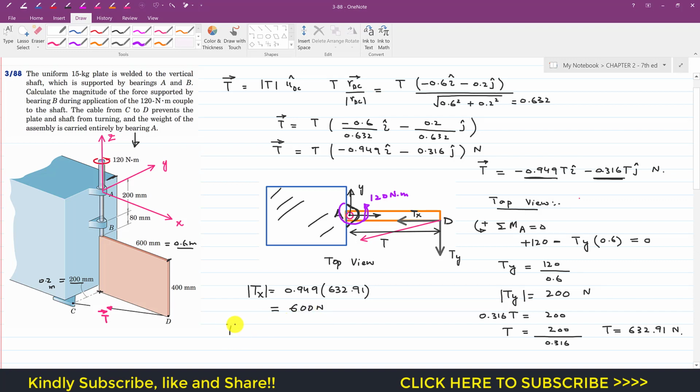Now we can write that the T Cartesian vector is equal to: Tx is 600, acting in the negative x, and minus Ty is 200 j. So this is the tension T in that DC cable which prevents the plate from rotating about the shaft.